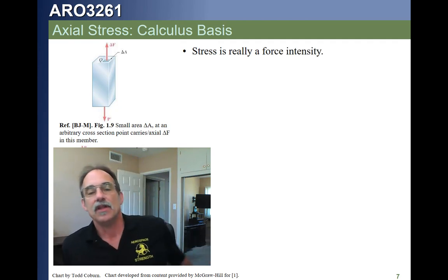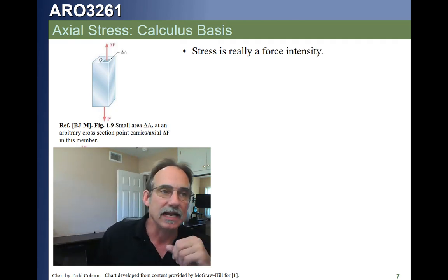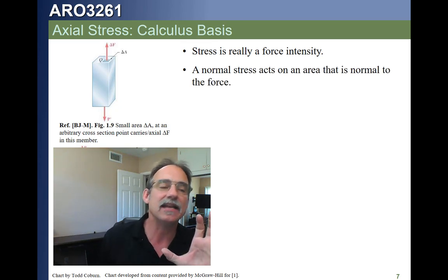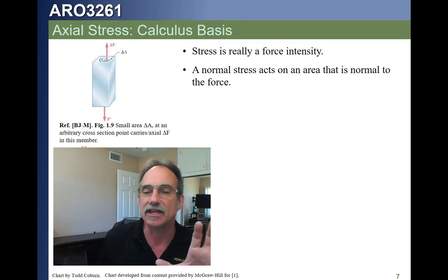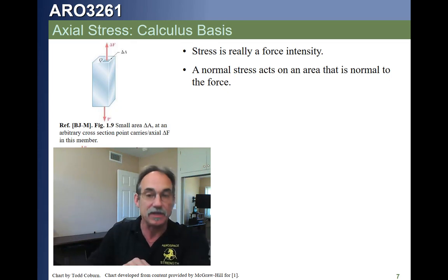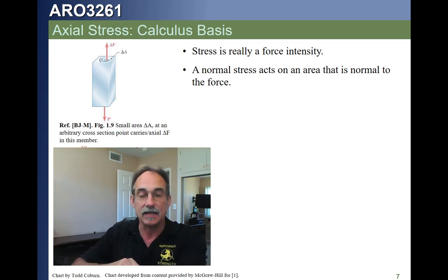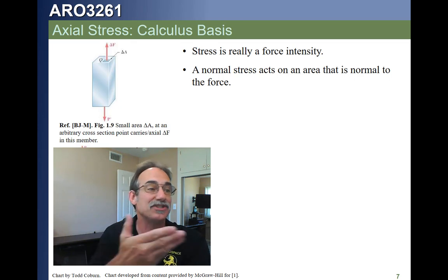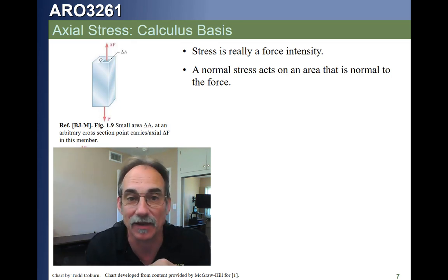Now, stresses, even though we did a simple P over A kind of check, we know that stresses are force intensities, and that it doesn't just magically get uniformly distributed throughout the structure. For example, if you pinch a piece of your arm and pull on it, you're going to find it hurts, and it hurts more, and you get more deflection right there in the vicinity of the load, and out away from the load you don't feel it at all. Structures are people too, and they do the same thing.